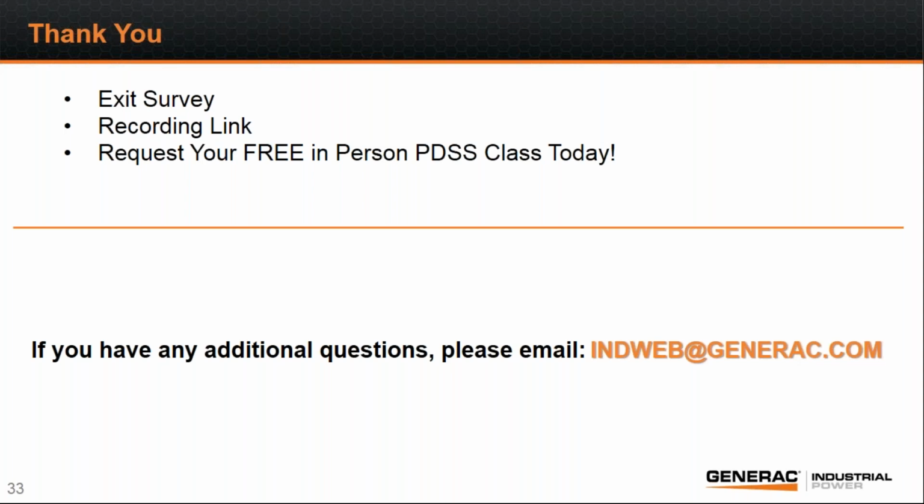And at the end of the day, now you're making a pretty significant transient on the genset. And until you get the right technicians out there to adjust the soft starter, there's usually a little angst in the marketplace. Some of the low-end soft starts may not give you the ability to ramp voltage.